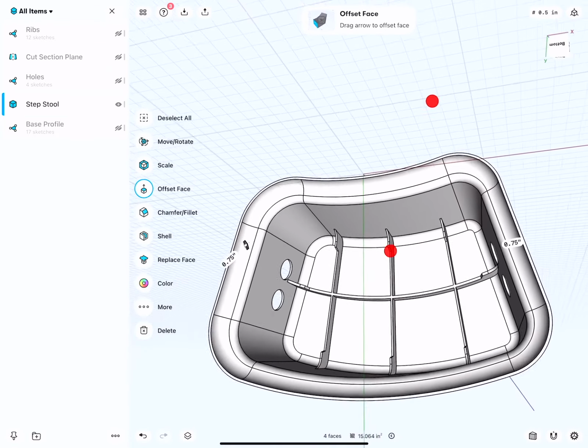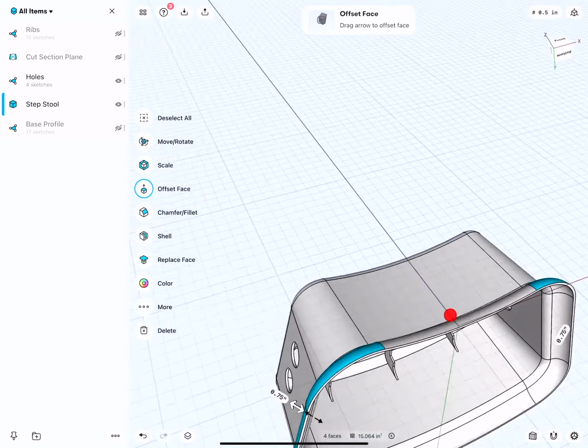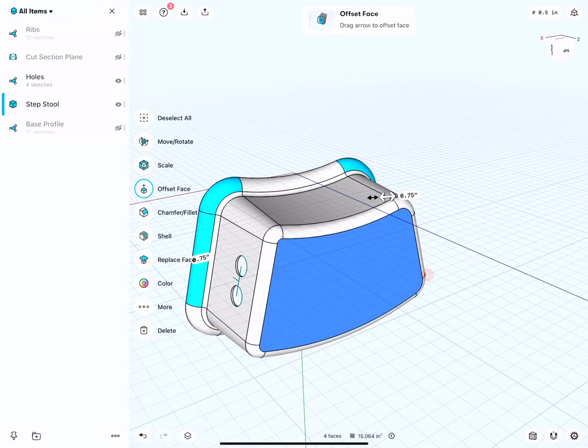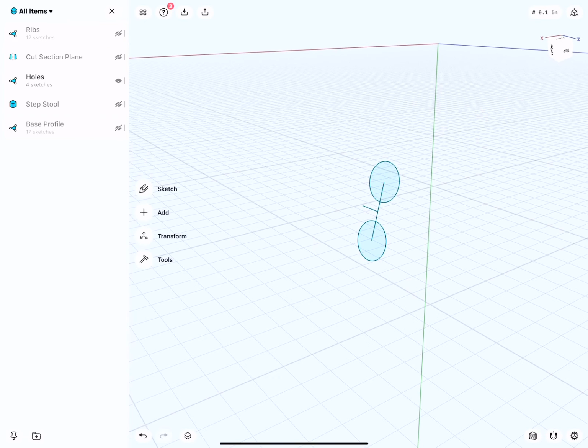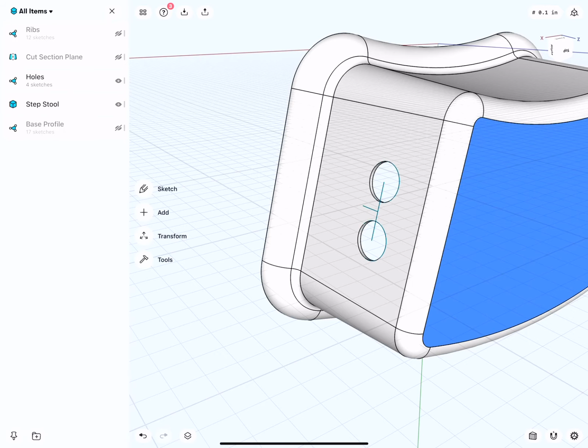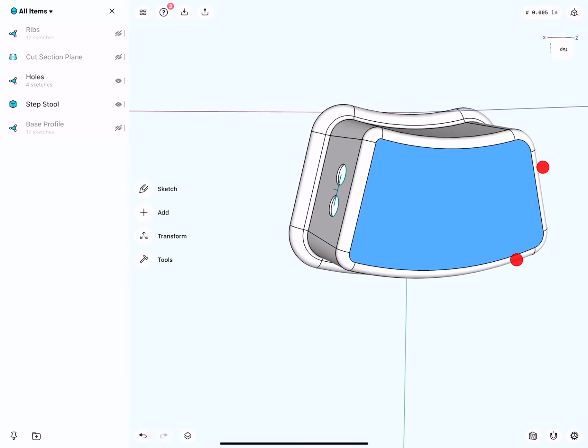The inside is empty, so it's kind of like a shell, because I built this first as a solid and then I used the shelling command to core it out. I put a sketch also onto the sides to model the holes. Very easy. I did this on each side. I built first two cylinders and then mirrored them over, and then I used the cylinders to cut each side. This is the reason why I only have one sketch.